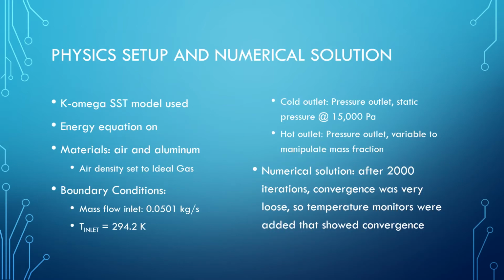I set up the physics by first setting the K omega SST model, turning the energy equation on. Kept the materials as air and aluminum, but I did set the air density to ideal gas, since compressibility is a huge factor in the proper operation of this device.